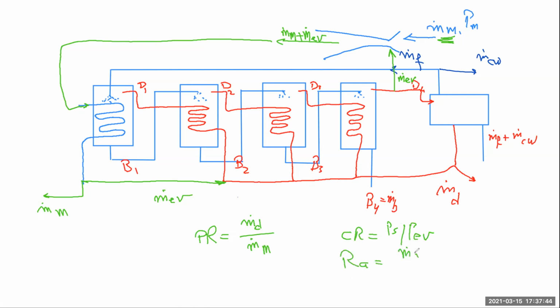We have the entrainment ratio, m dot motive over m dot entrained vapor, and RA is obtained through a correlation that is a function of the motive steam pressure and entrained vapor pressure in addition to temperatures. And we have the pressure and temperature correction factors. So this is something that you have seen before. The only difference is that it is associated with a multi-effect desalination system.